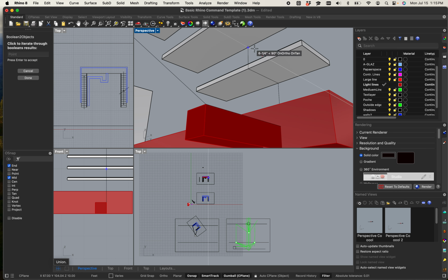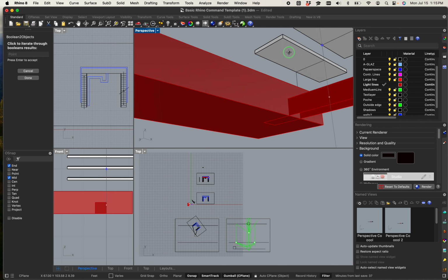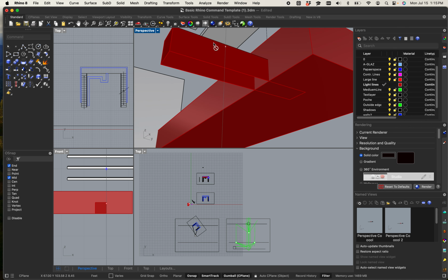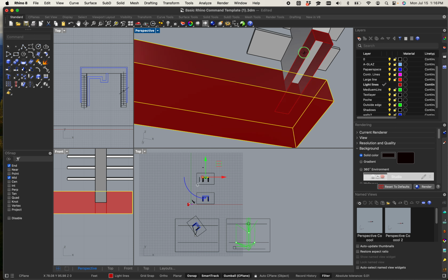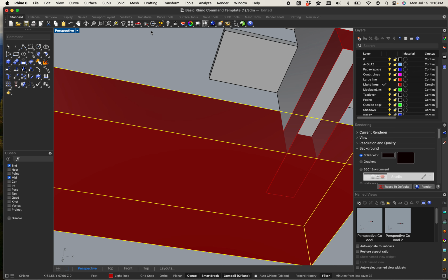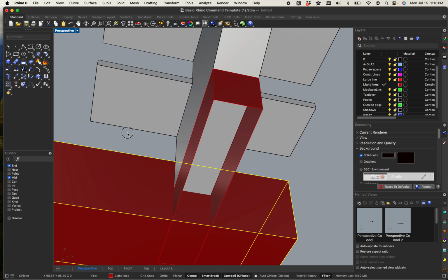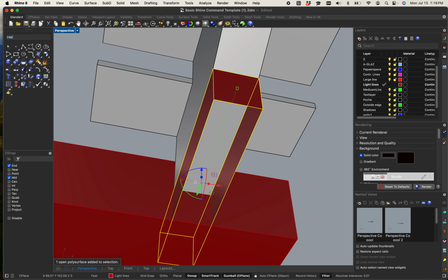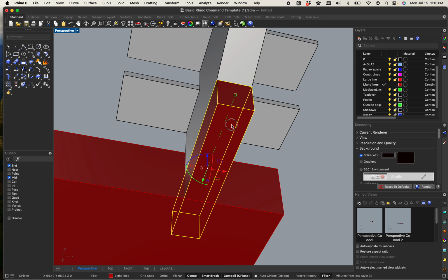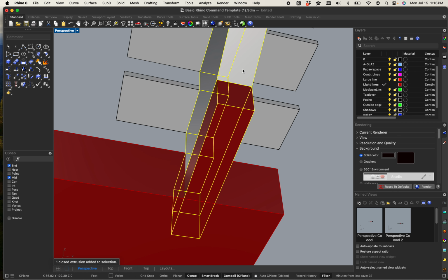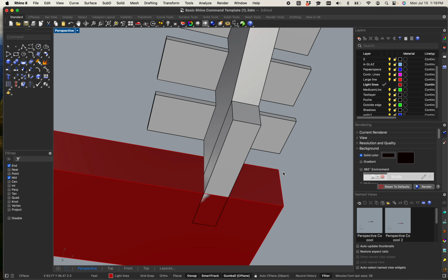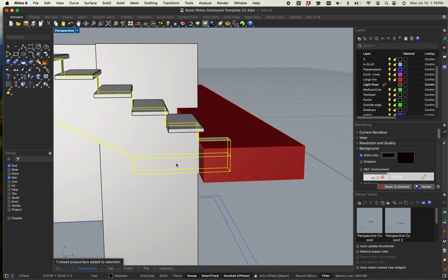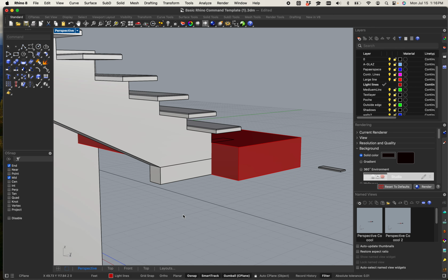Obviously, if I put two of those devices together, in my case, it doesn't look like it was a closed box, and that's maybe why it's giving me some issues. Don't get me wrong, modeling is a little bit on the A team for a reason. We have to be a little more aware of what's going on in the model. So in my case, I needed a closed box first, so I need to cap it. I'll take that cap, take that piece, and try boolean two objects again, or in my case, boolean union. That's another way to put two objects together. And as you can see, it immediately comes together into one object, and it keeps those lines there as well.